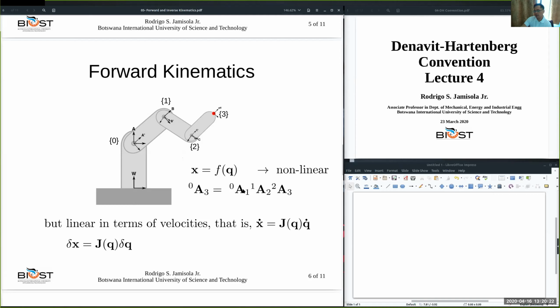Okay, and we note that this is the forward kinematics that we are talking about, where in this case, the transformation matrices are functions of the joint values, the q. All these transformation matrices A can be solved when you are given the current value of the variable q, which can change at a given time. And so with this post multiplication, we can find the orientation and position of the robot end effector frame at any given time as the q changes.